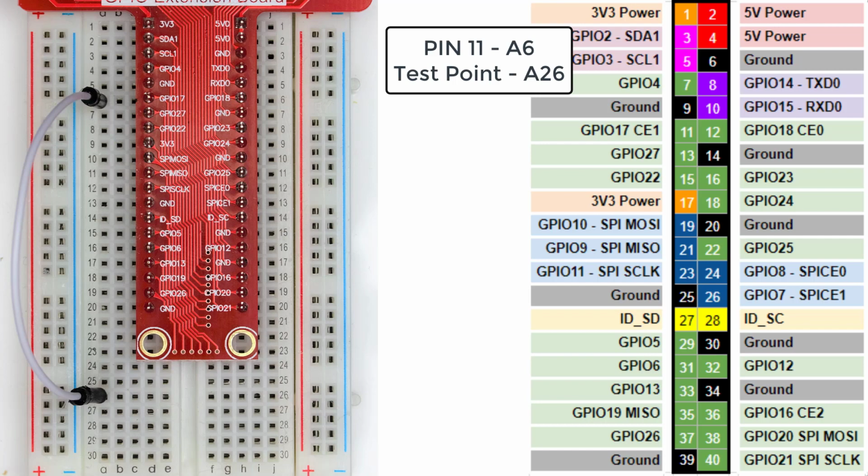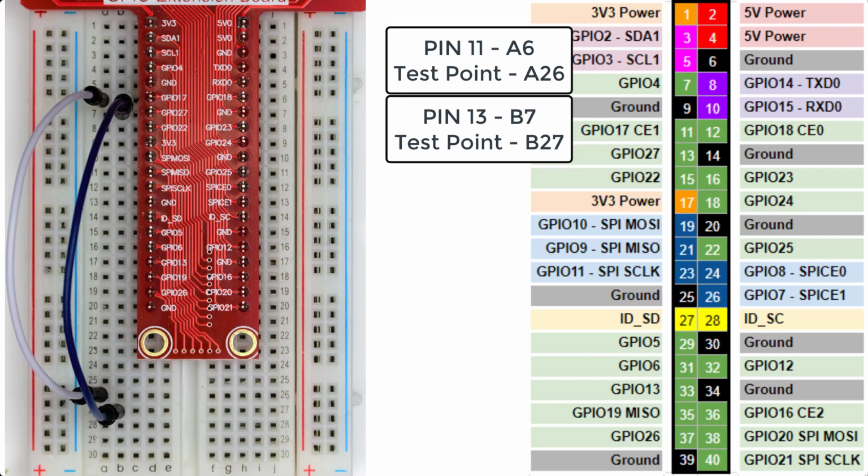I've just been calling them out specifically because we're going to have several jumper wires on here, and I want to make sure that you have the same value as I do. We'll next create a test point for our pin 13. So I'm connecting GPIO 27, which is physical pin 13, at B7 down to the test point at coordinates B27.